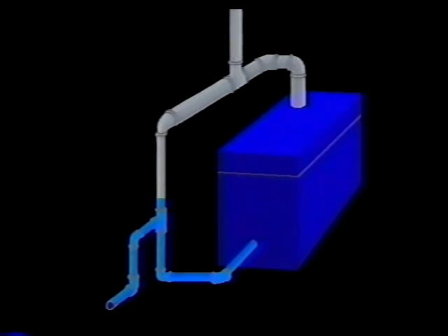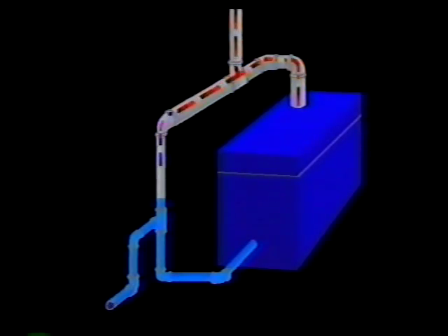If we look at this example, we can see from the water levels in the boiler and at the short nipple that the boiler pressure at the water line and the pressure at the short nipple are equal due to the equalizer line. If the water line drops to the level of the short nipple, no more water can be forced from the boiler. Or if there's a break in the return, the boiler can't be drained. Also notice, any condensate accumulated in the header is returned to the boiler through the equalizer.